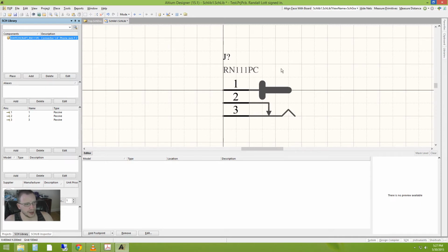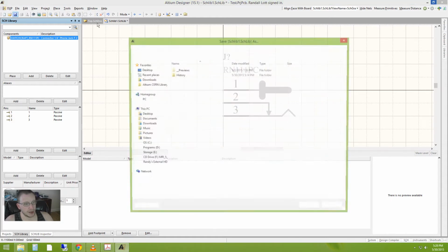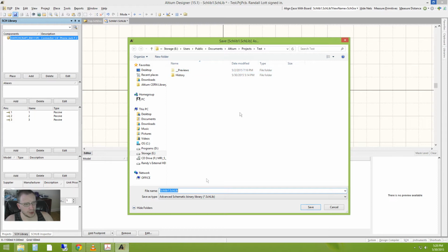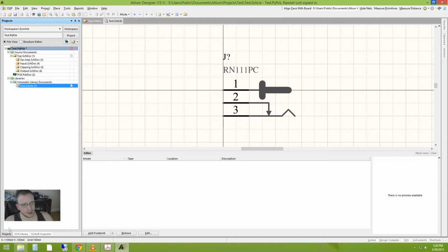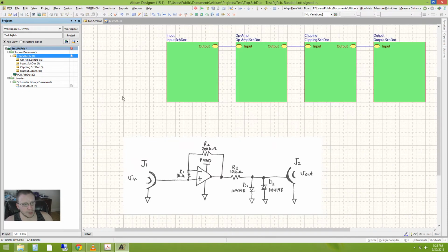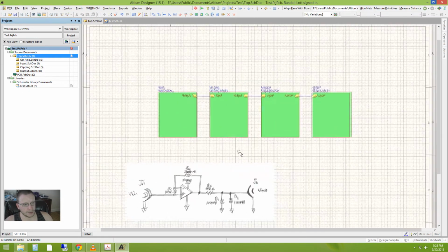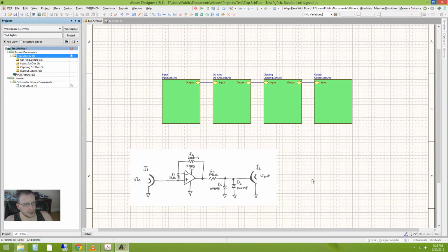We have the diagram with the pin numbers. That will actually translate to the physical footprint on the circuit board. So these have to be correct. You have to know that. If you're having trouble with it, a lot of suppliers will help you out with it, but it's a skill that you really need to learn if you're going to be doing this a lot. It would be a very, very costly mistake if you get a board back and you did that wrong. So don't do that.